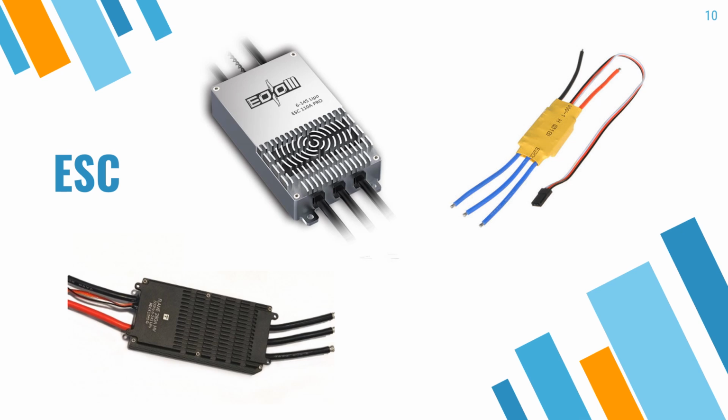Alright, as promised, the ESCs. ESC stands for Electronic Speed Controller, and by applying different voltages to the motors, it's capable of controlling its speed, or angular velocity to be more precise. An ESC is chosen for its maximum current it can handle. For example, if you look at the ESC above in the right corner, this one could handle up to 30 amps, and actually that's also suitable for our DronoBox drone.